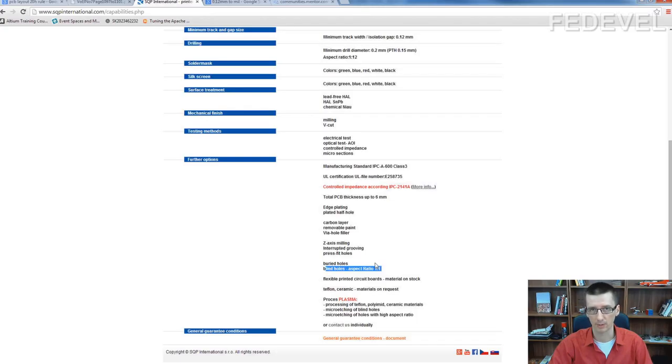the thickness, because we are using a 0.1 millimeter micro via hole, the maximum dielectric thickness which they can drill plus the copper will be 100 micrometers. And if your microvia is deeper, if you need to drill through 200 micrometers, then the microvia hole size needs to be 0.2 millimeter. You really need to consider this when you are deciding on the microvia and through-hole via size.